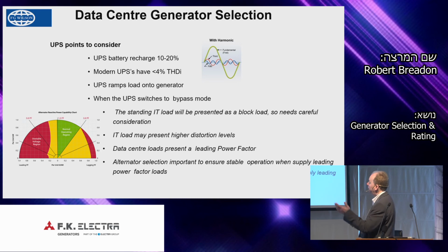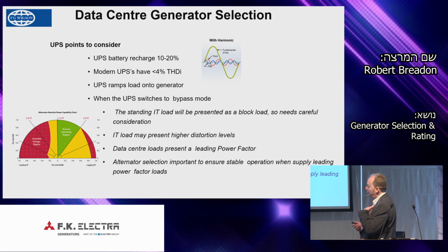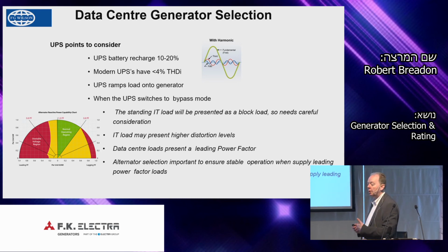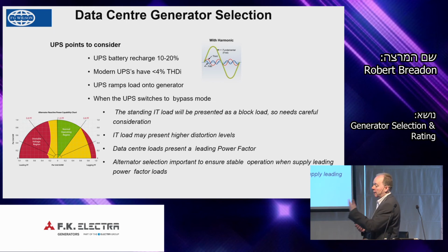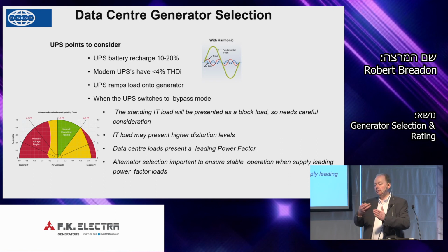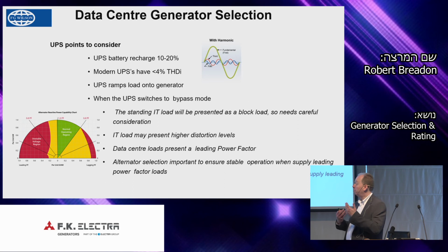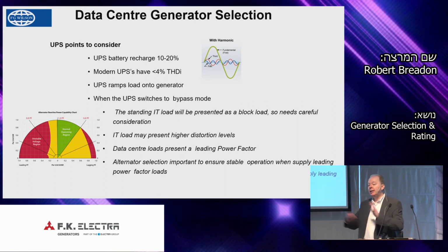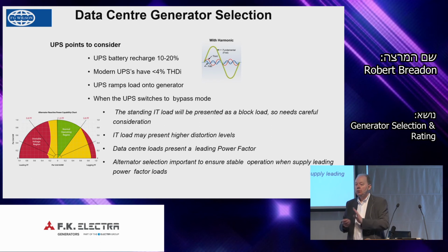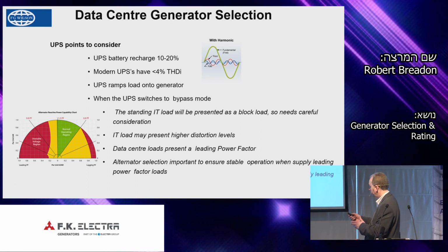I have seen in a lot of cases consultants ask whether the machines can operate at, say, 0.95 leading, because that's what they consider the bypass situation to be. Normally, when you're connected to UPS, you'll set about unity power factor, the most efficient level.